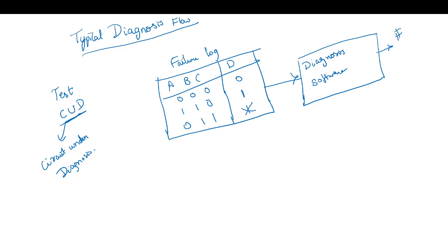Now for this we will have a fault dictionary. Say this particular fault is diagnosed. Like a chip is failing for this particular pattern, then which fault is responsible for that? So in that we will have the fault dictionary.